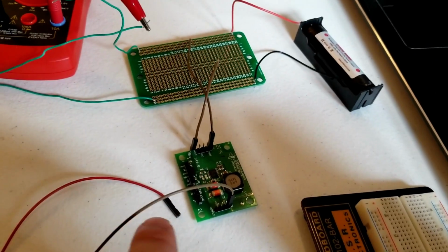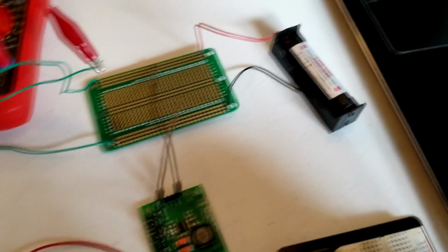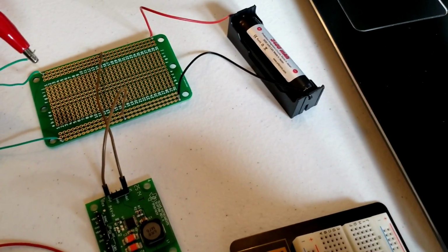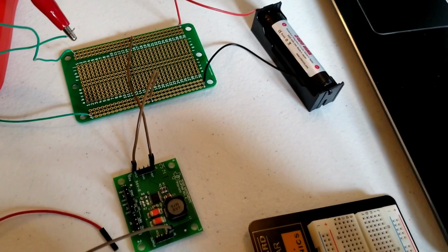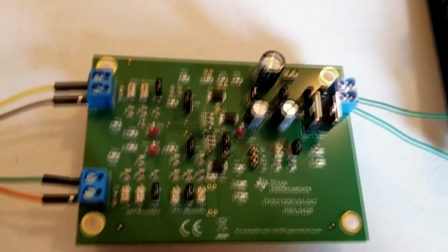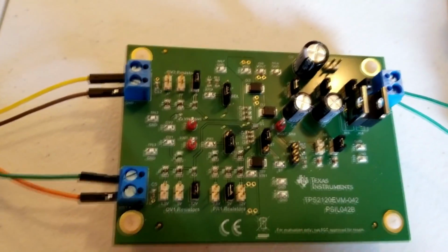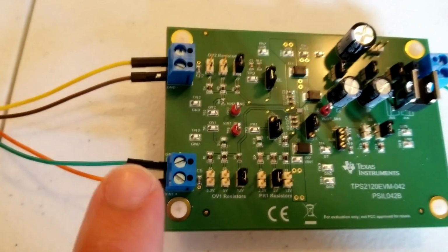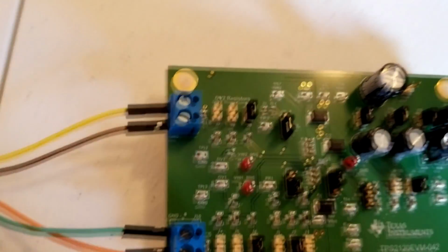In the case that the battery were connected across a load, it would be discharging across this boost converter, because the Orbtronic 3400 milliamp hour battery only outputs 3.7 to 4.2 volts, which is obviously not a voltage that we could use for a 5-volt system. So basically, we have to boost it up and also bring it back into this power mux, where it's set in a comparison mode right now. So if the wall power is off, it will switch over to the second input right here, which is the battery. Else, if not, it will only ever use the wall input.